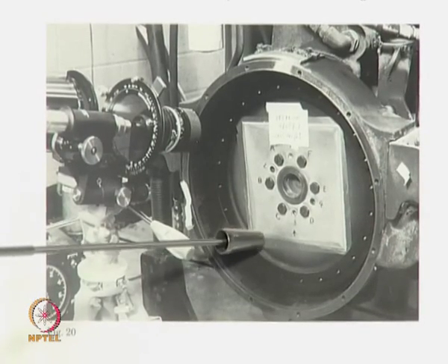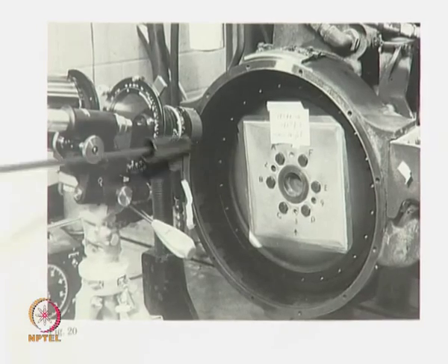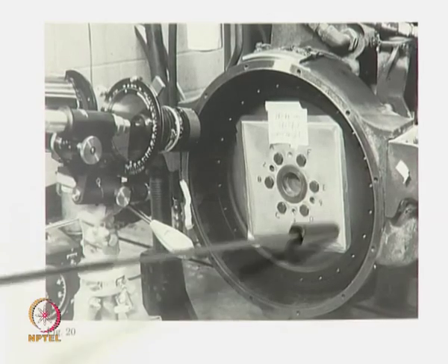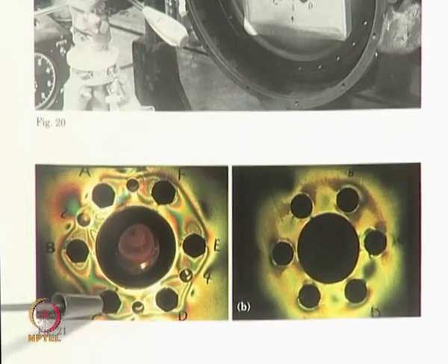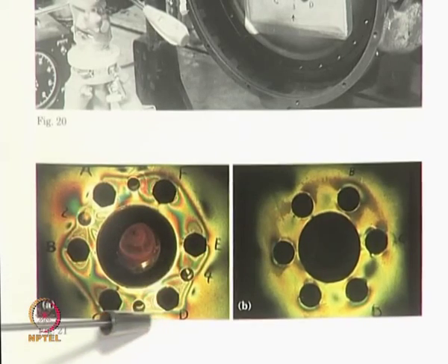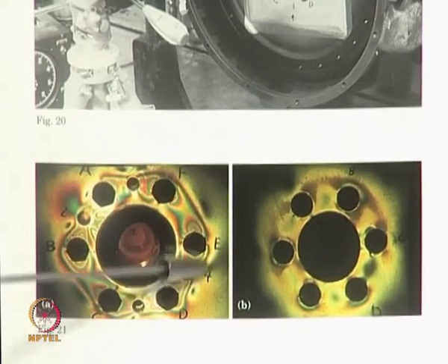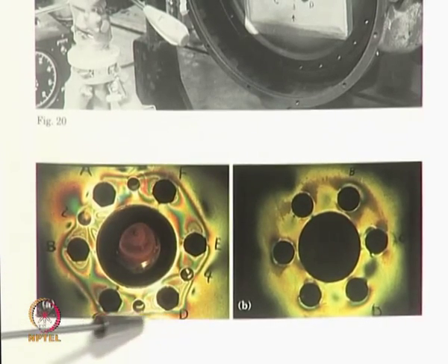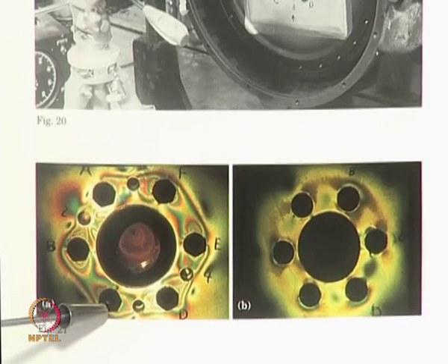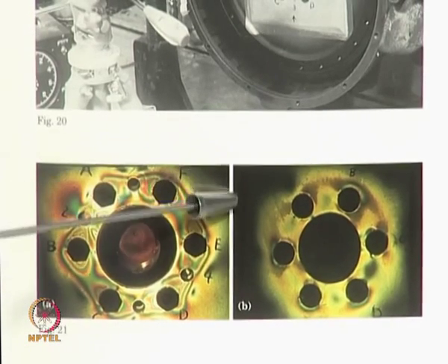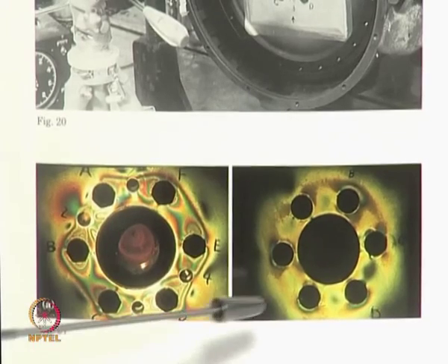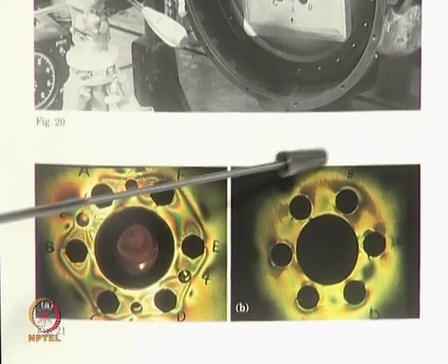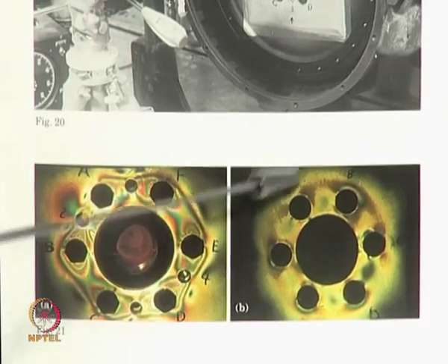This shows another example of application of photoelastic coatings. Here you have a flywheel that is being analyzed. I had mentioned that when you see colors, you have to be worried in a photoelastic coating test, that indicates the stress levels are very high, and this is the initial design of the flywheel, and these are the stresses due to assembly. Based on this input, when the design is modified, you have the final set of assembly fringe patterns which are very good from design point of view.